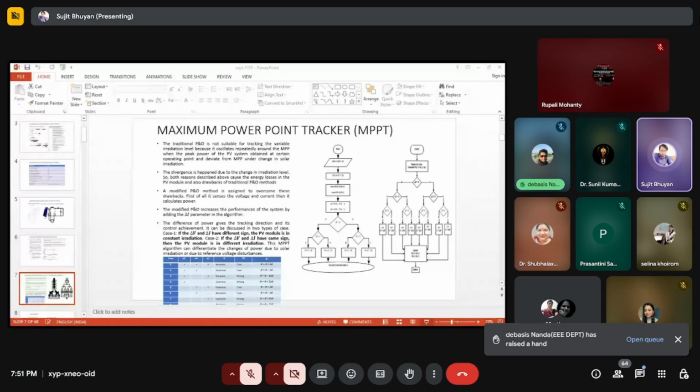So go for the modeling of the BSU, the battery storage unit. This is the mathematical modeling I have given you, and these are the specifications I have used to model the BSU. This is the nominal voltage of 750 volts, and the capacity is 35.7 Ah, where Ah means ampere hour. Always remember, for a battery we take the ampere hour. And the SOC level, state of charge, is 90%.